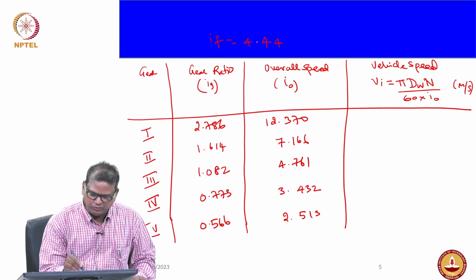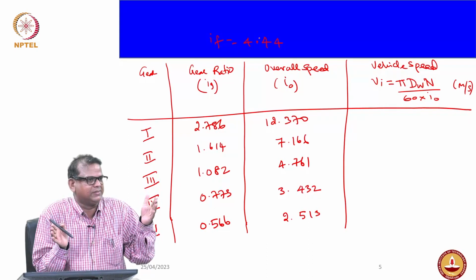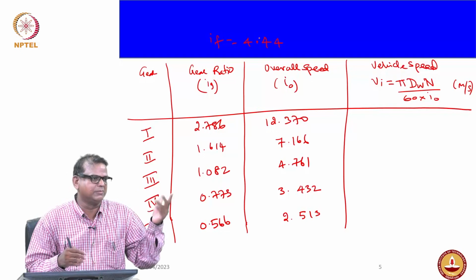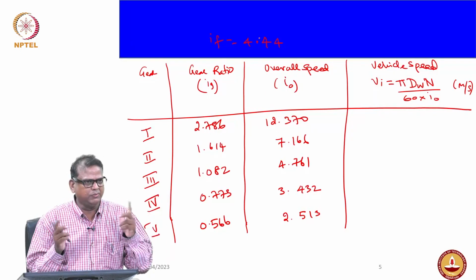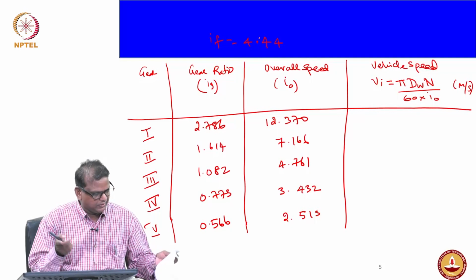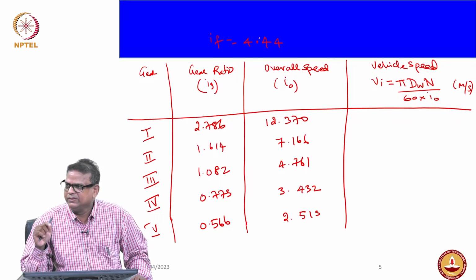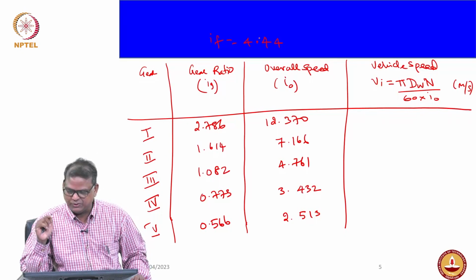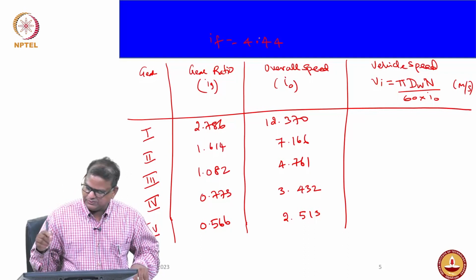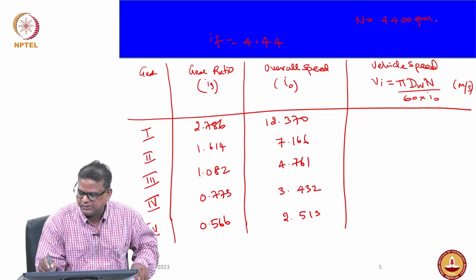You can have two approaches. One is the torque aspect. Otherwise, if you want to understand the maximum possible heat generation, in that case you can go for the maximum speed, the maximum power condition. Two ways you can solve. However, I am going to solve with the maximum torque condition. So, N will be 4400 rpm, that is the maximum torque condition.